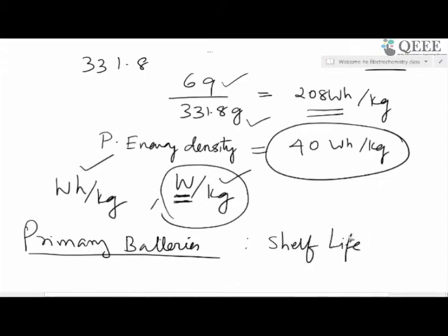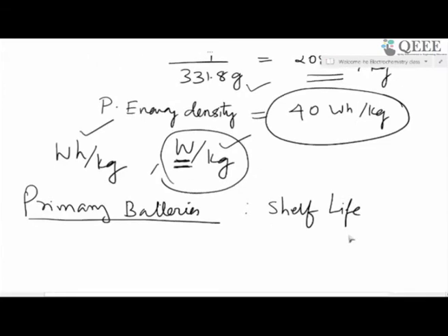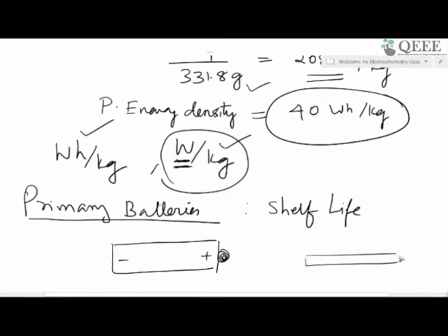Just like the alkaline battery where I use zinc as one electrode, the other is MnO2. If you ever break open these AA or AAA batteries, you would see in the middle there is a carbon rod, and then you have a tin made of zinc, and the MnO2 in alkaline medium is kept inside as a gel.